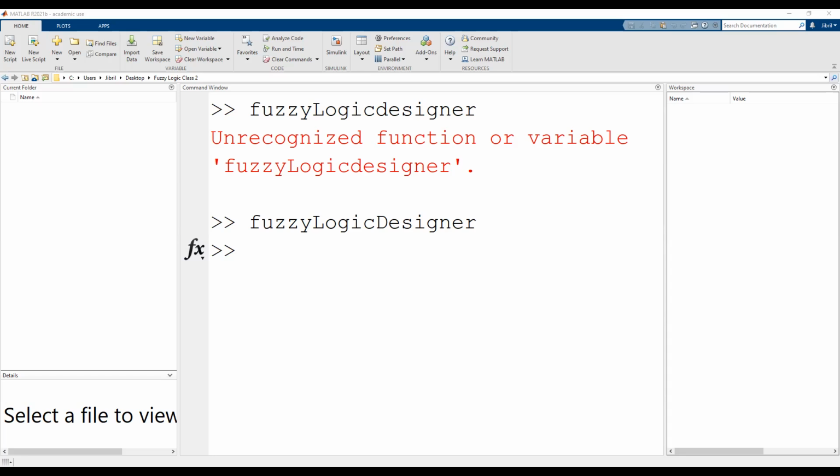Pretty basic. So in that case, we can design the fuzzy inference like this. The first thing you need to do is clearly define what your inputs and outputs are. So here we have input 1 and here we have output 1. Basically our input will come from the temperature sensor and the output will be the fan.